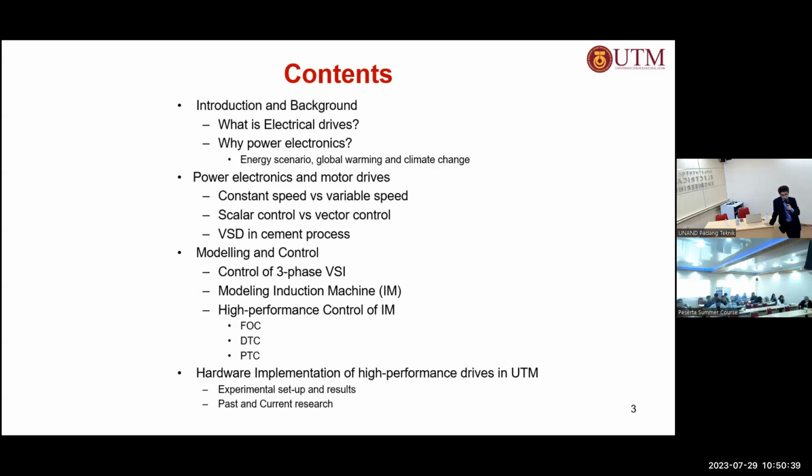And then the heavier part is on the modeling and the control of the induction machines. We are going to deal with mathematical equations, modeling, and then we see how, by manipulating these mathematical models, we'll develop the control systems used for the high performance control of induction machines, which is the field oriented control, FOC, DTC, direct torque control, and predictive torque control. I will probably not have time to go through all these controls, but the slides are there. You can refer to them later. Probably I will just pick one of them depending on the time, okay?